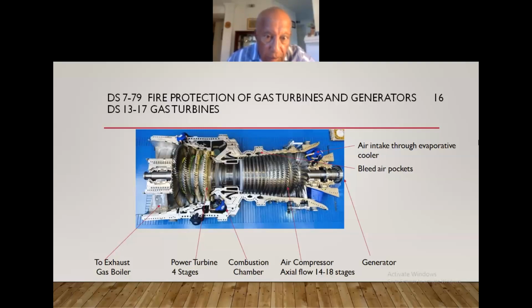Now think in terms of these blades. They're spinning at 3600 RPM. That is a huge centrifugal stress. And also there is an axial thrust, which is creating a torque on the turbine, and also the 2200 degree Fahrenheit gas. Not many metals can withstand this kind of harsh treatment.